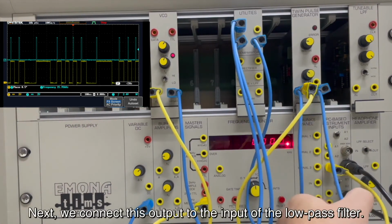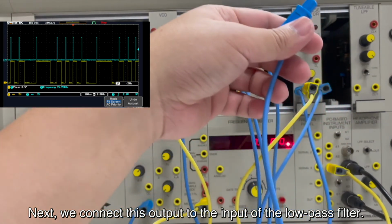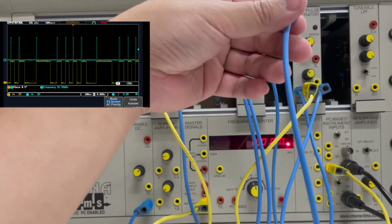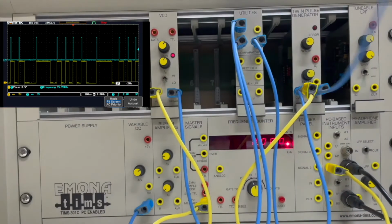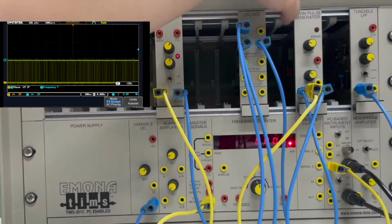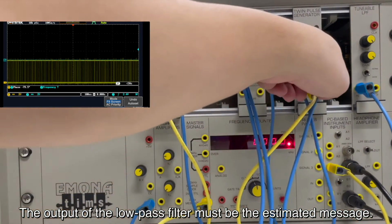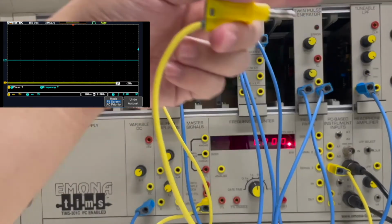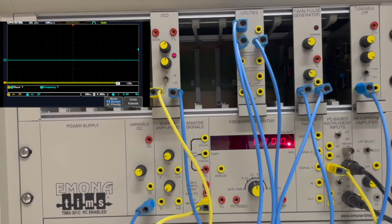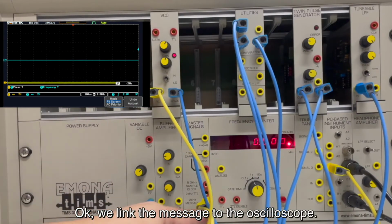Next, we connect this output to the input of the low-pass filter. The output of the low-pass filter must be the estimated message. Okay, we link the message to the oscilloscope.